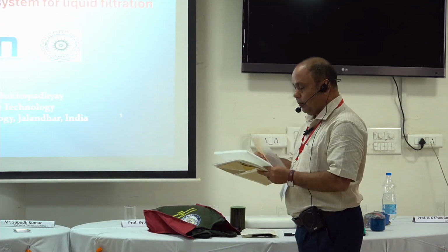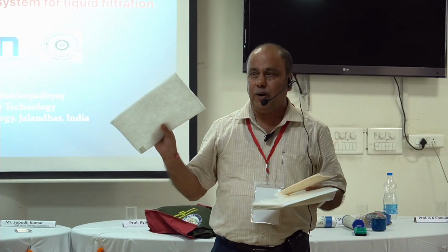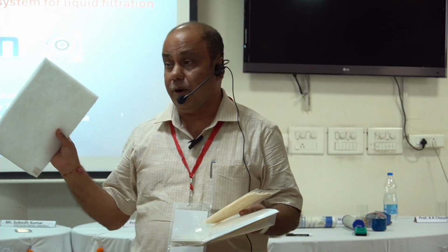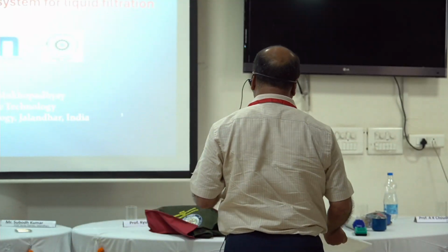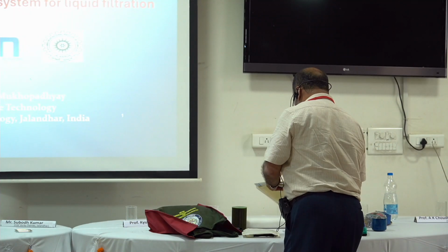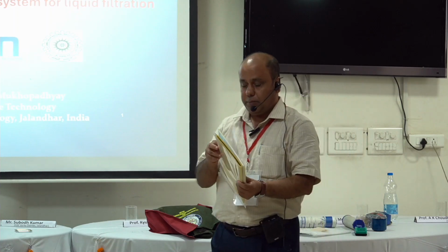Now I am just showing you one of the pre-filters. This is a pre-filter for air. But why am I showing this? Because this cannot be used for a liquid filtration application, because it will be choked immediately, within a few moments. So the filter media applied for liquid filtration applications has to be very compact. I can show you some of the filter material.